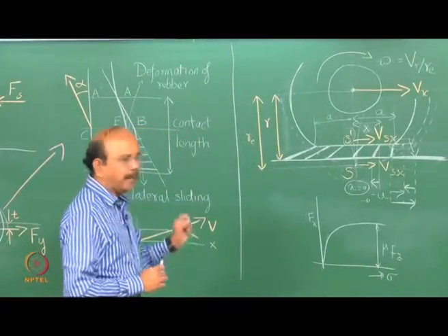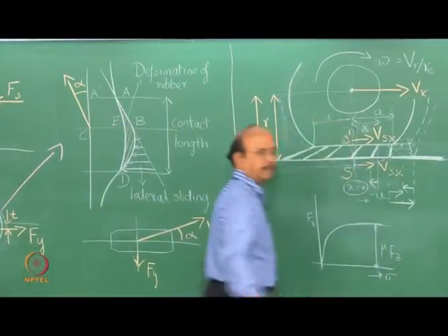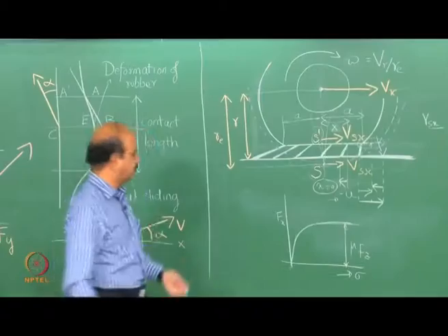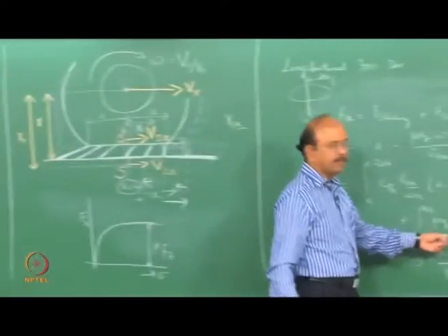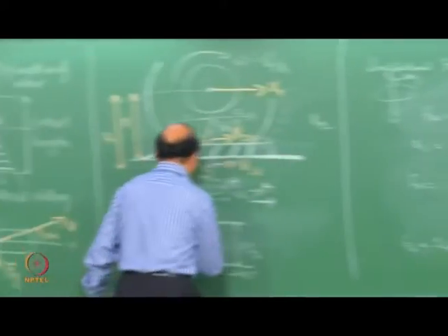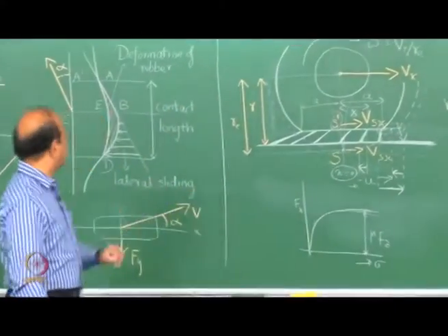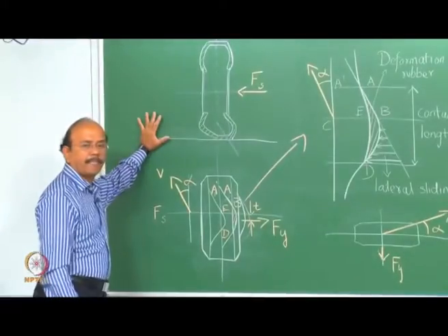Okay. Now practically, this may not be a straight line. And that's because we have assumed mu to be a constant, but there's going to be heating and there's going to be dynamic friction and so on, and usually the mu here as a constant may not be valid, and you would have a drop here. We would talk about that again in the next class. But before that, let us now look at the lateral deformations.